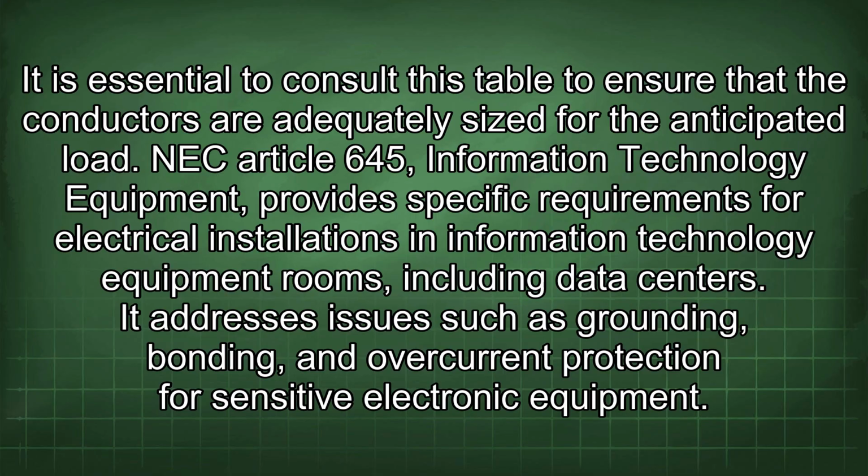NEC Article 645, Information Technology Equipment, provides specific requirements for electrical installations in information technology equipment rooms, including data centers. It addresses issues such as grounding, bonding, and overcurrent protection for sensitive electronic equipment.